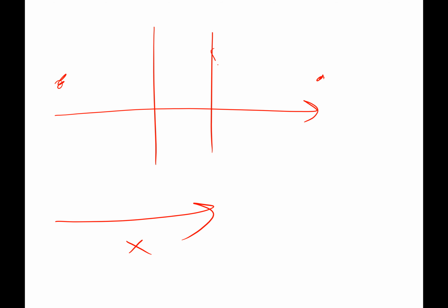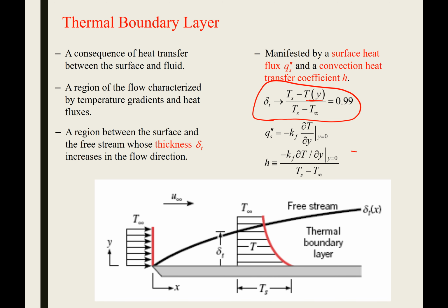Even here in the boundary layer, we would still expect our flux to be constant, which allows us to do something like this, based on an energy balance. If you rearrange the terms, you would see Newton's law of cooling: the convective heat flux is equal to Fourier's law of conduction, except now we're talking about conduction through the fluid itself. Notice that k sub f is characteristic of the fluid's thermal conductivity.